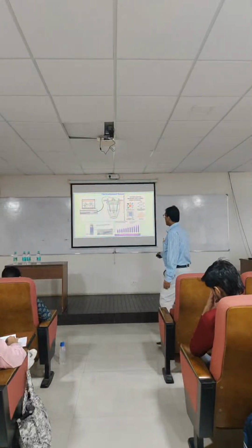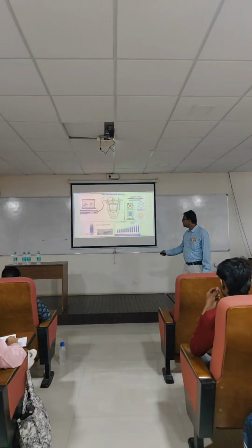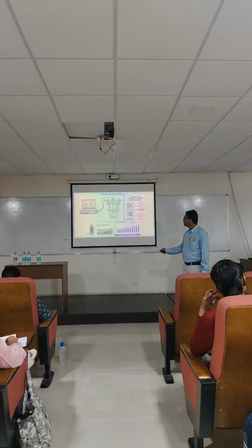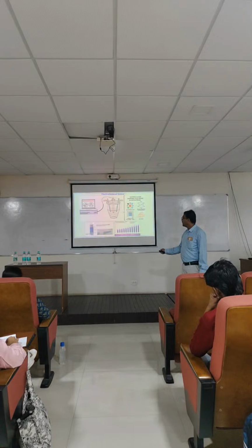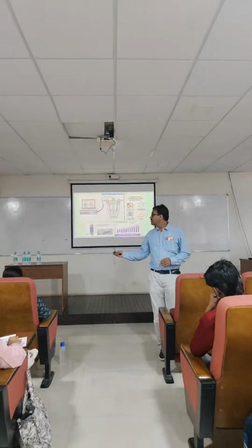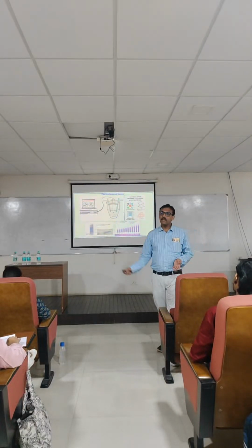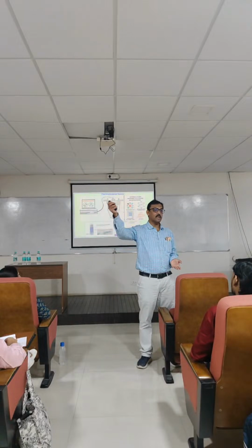Okay, this kind of strip, and here also you will be getting the 3 electrodes. As you can see here, this is the point where you can put your analyte, and this is CE, which means the counter electrode, WE means the working electrode, and then this is the reference electrode. So it is the same system, now integrated into a miniaturized system, and then you can take it into the field and you can create a signal.